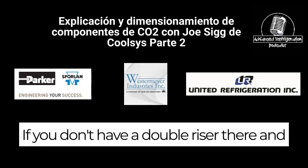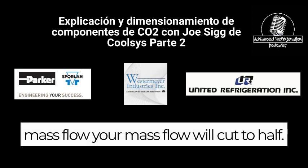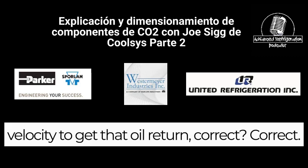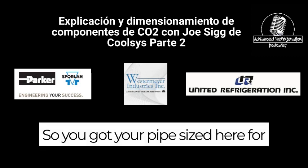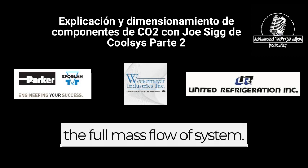If you don't have a double riser there and 4 of those cases shut off on satisfaction, your mass flow will cut to half. Your riser won't be sized properly to get that oil back up, because you typically need X amount of velocity to get that oil return, correct? Correct. And the neat thing about a double riser is just the way it operates. You've got your pipe size here for the full mass flow of the system. The trap here is sized for the full mass flow of the system.